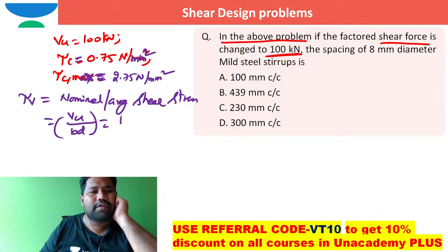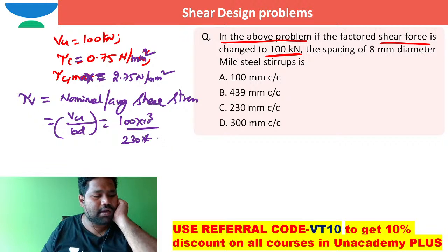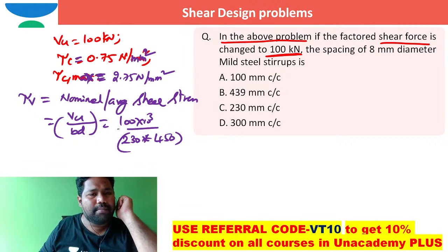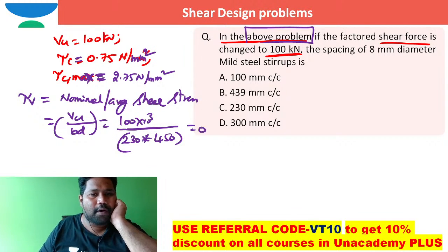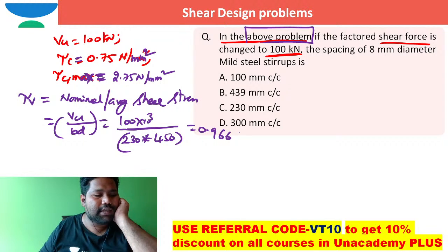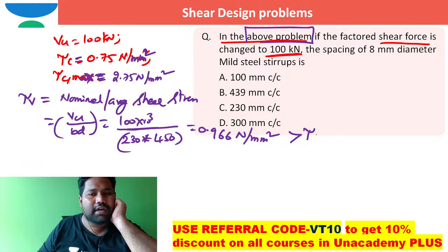What is that value of Vu? 100 into 10 cube by b. Width is 230 millimeter and the effective depth d is, I think, 450 millimeter from the previous problem. So I am taking the same thing because in the above problem they mentioned. If I work out, this is 0.966 megapascal. Here tau v is greater than tau c and less than tau c max.